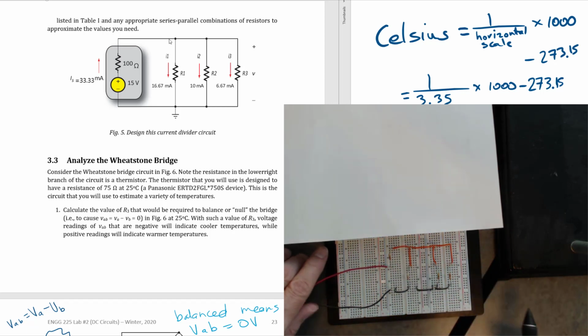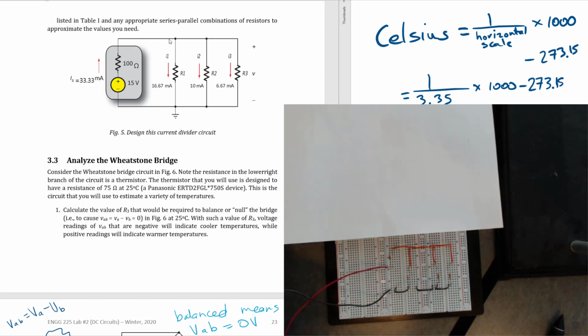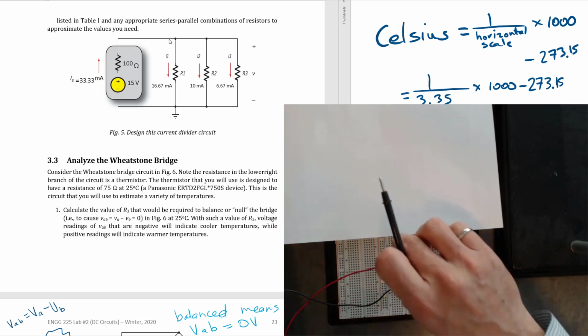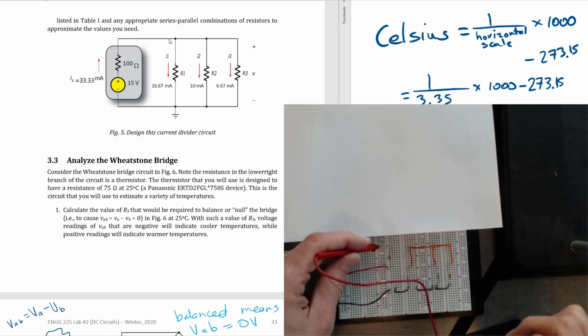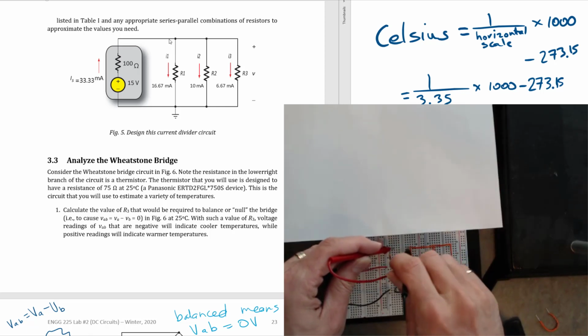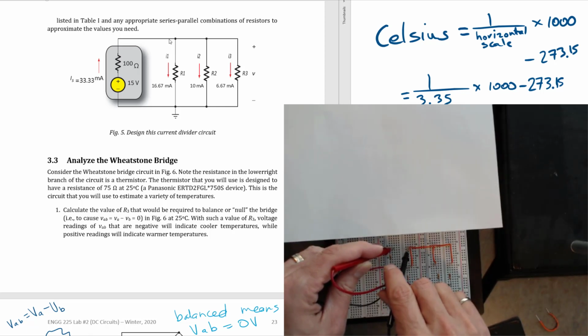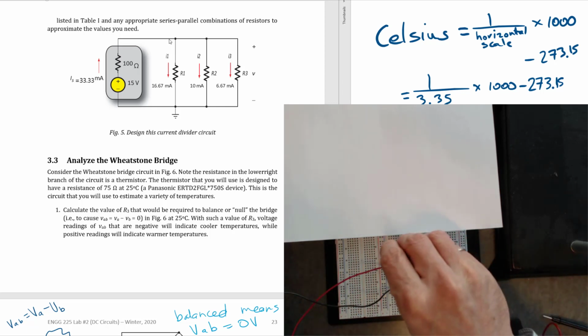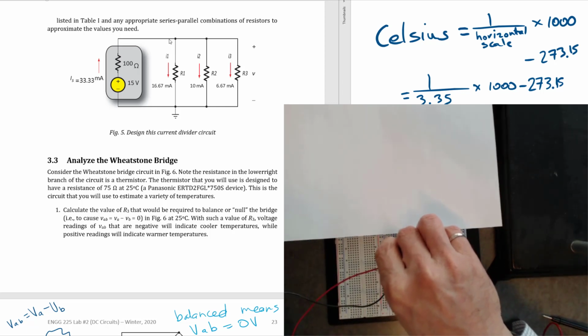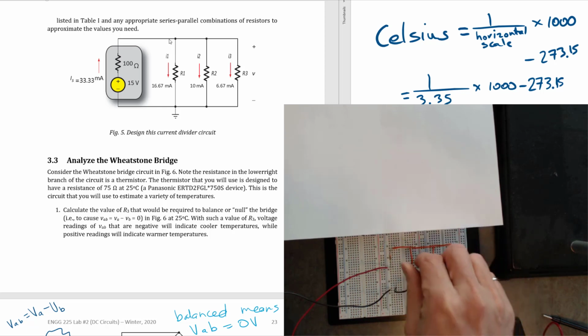And the reason why we've built it this way is that we're going to come across and measure the currents. So let's say we want to measure the total current. We could take this jumper out and measure the total current going across something like this, okay? So we can selectively take out the jumper wires and measure the current.